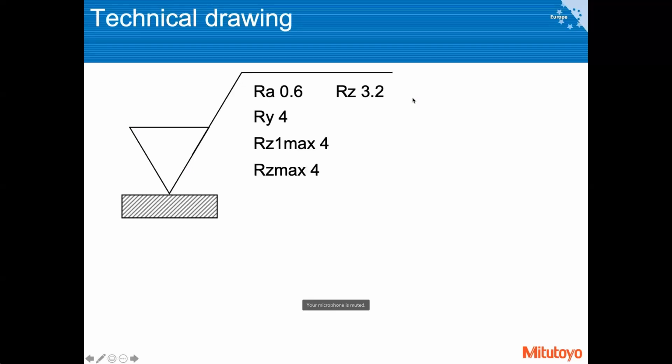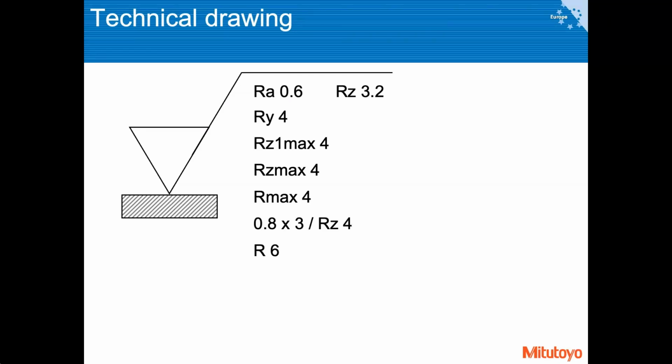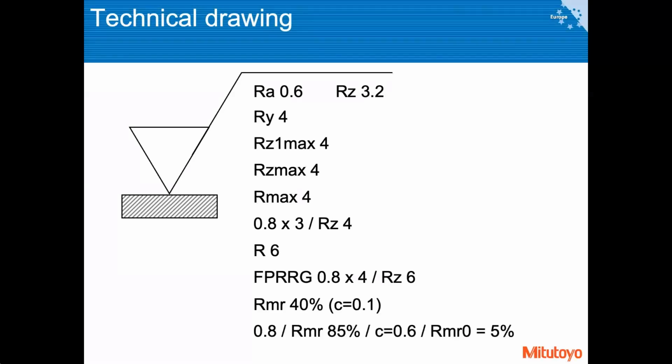Additionally, you can add tons of other things you want to measure, but I'll be honest, it is almost impossible to produce parts which ask for various texture parameters to match certain requirements, because a lot of those parameters are mutually related. If you change one, the other one changes accordingly, and thus you can only stick to the one which is the most important for your case.